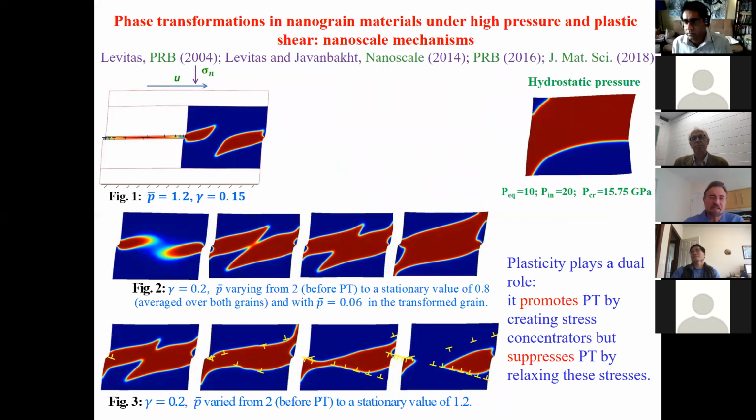Well, it affects. First, yes, we consider dynamics. That means that it evolves. It starts from, for example, here it starts from a dislocation-free sample. Actually, we always start with a dislocation-free sample. Then dislocations nucleate, the number of dislocations increases, and we study this in detail. For example, dislocations produce a very small nucleus, then when the number of dislocations increases, it grows. Then if they are close, they coalesce. But yes, it's a dynamic process.